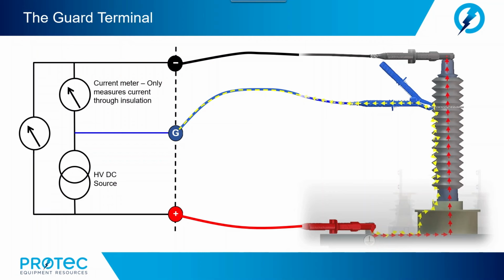Now, some insulation resistance testers have 2 terminals, others have 3 terminals. As these are DC testers, two of the terminals are the positive potential and the negative potential. The third, if present, is a guard. It does not have to be used, and many operators use insulation testers satisfactorily without ever employing the guard circuit. However, it affords the operator an extra function of diagnosis of equipment problems.